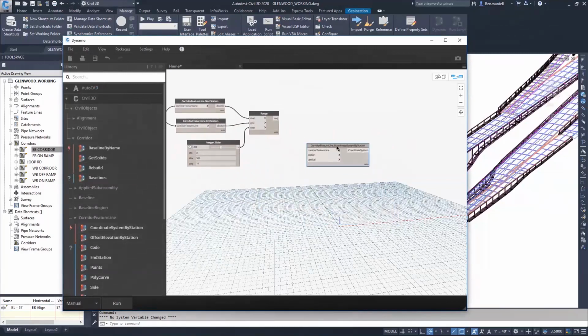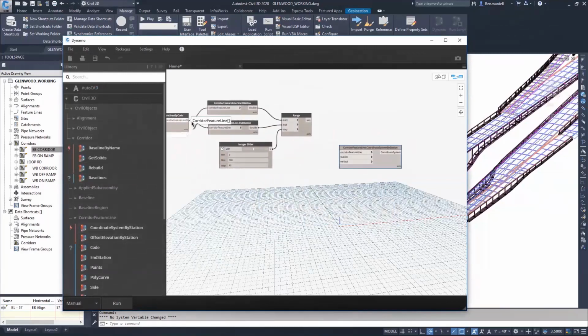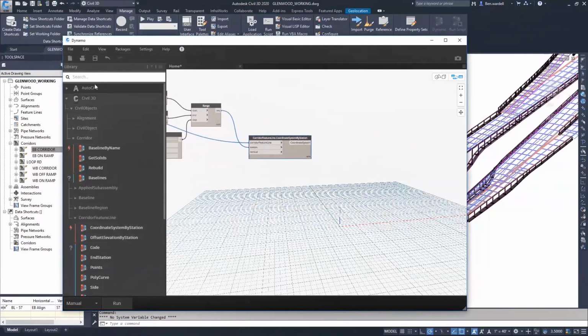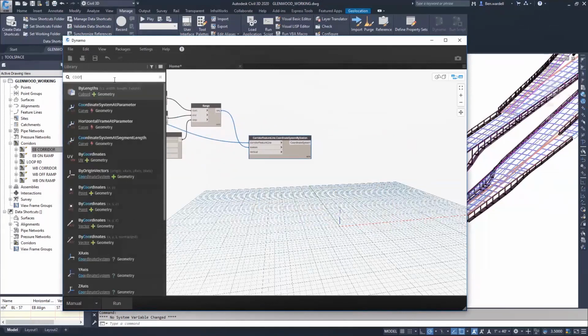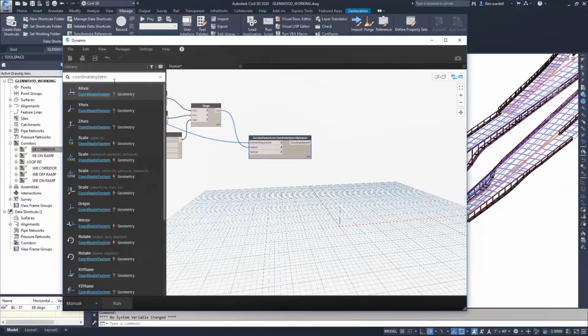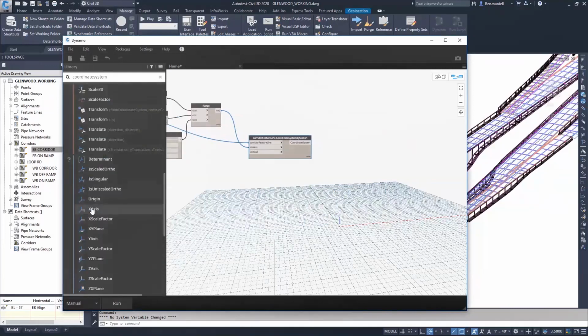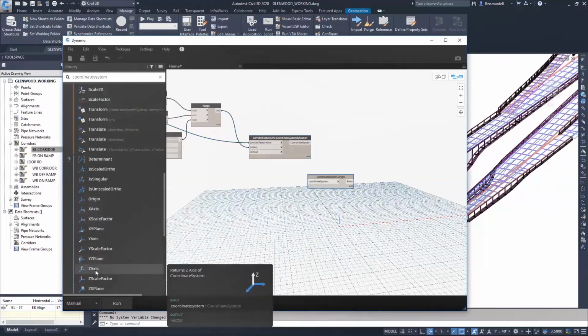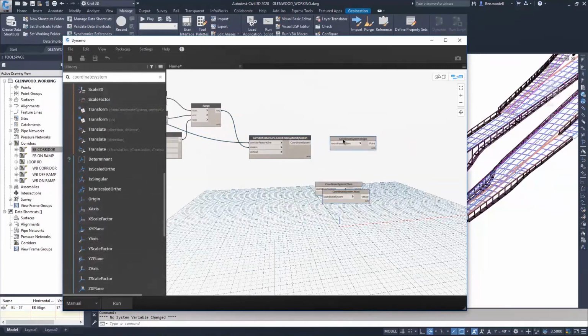You can go further, after having defined the frequency. You now need to associate the start and the end with a specific position. Now that you have defined that I want to have them at 200 meters along the corridor spacing, at what specific station, in terms of elevation and X, Y along that particular corridor, am I going to have them? In this case, you can choose a specific origin along the Z or Y, or a combination of X and Y plane, and choose the corresponding elevation.